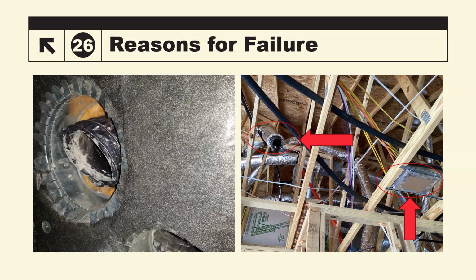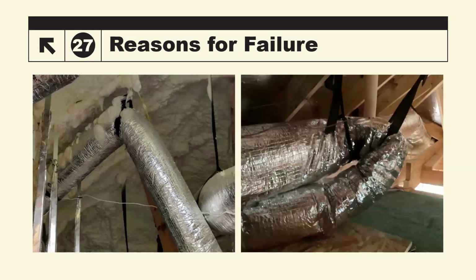But these, again, you should not and you are not allowed to get up there and tape this up just to get a passing duct score. It needs to be fixed. And of course, the chance of allowing this to move forward without getting it fixed before sheetrock is slim to none. It can happen, but it's slim to none.